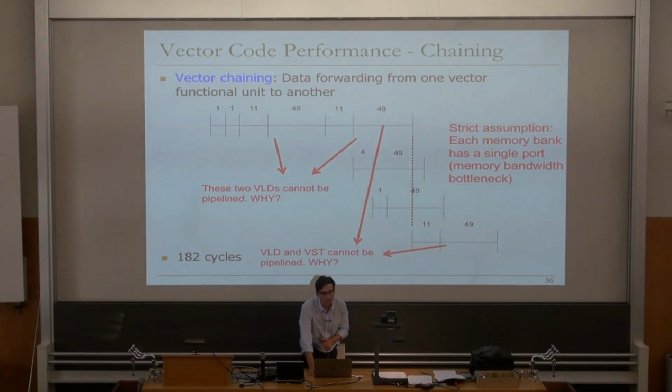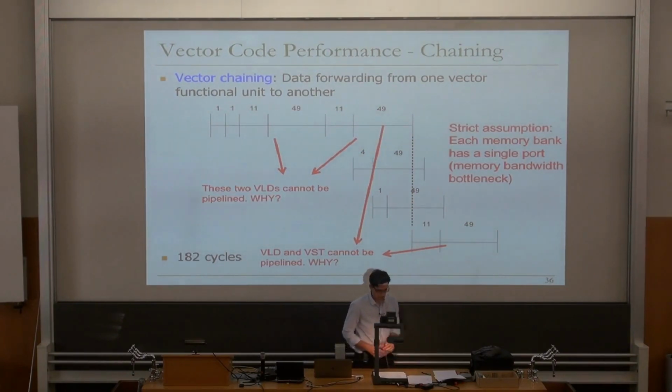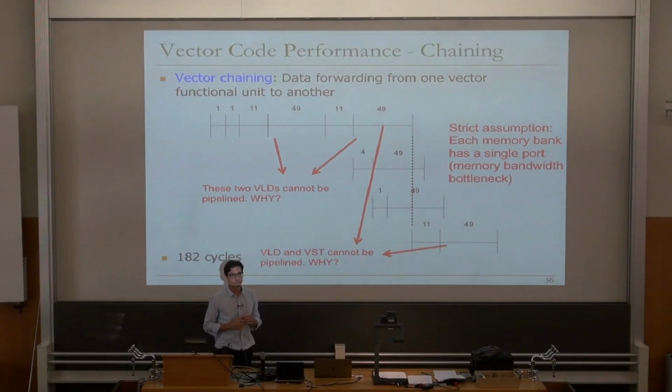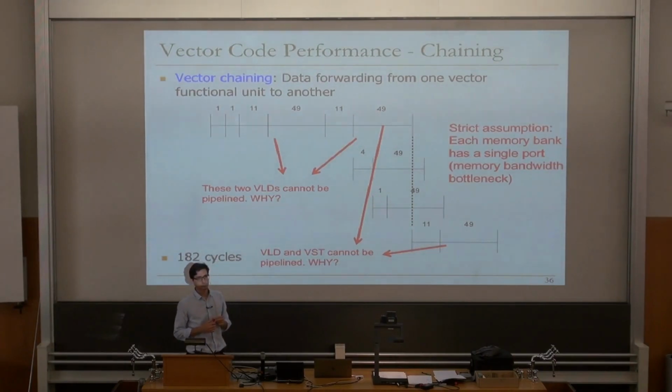Yeah. I mean, for data movement, I understand, but the addresses are also concurrently written out to the memory as data is moved out. The 11 latency and the 49, the addresses get written to memory simultaneously. So why can't the second vector load also continue writing these addresses simultaneously?